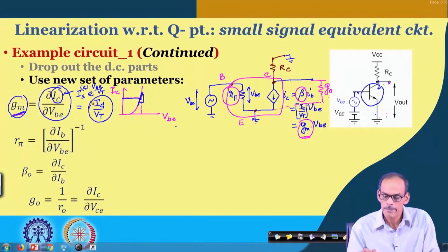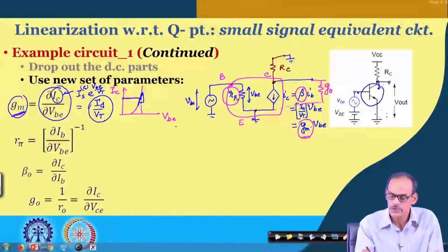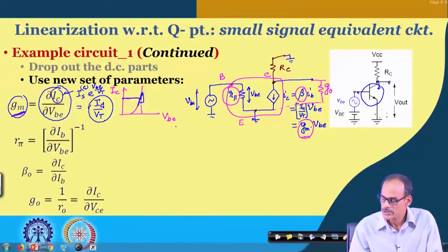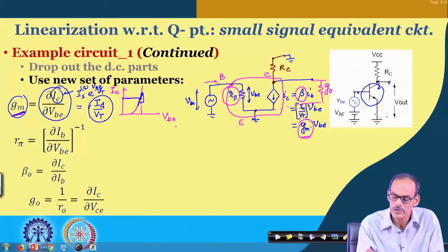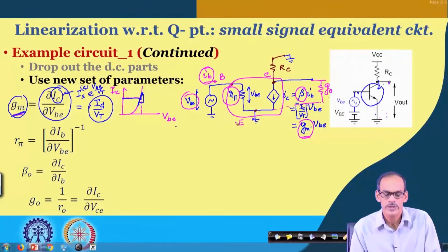On the other hand, whatever current flows through this circuit in the small signal equivalent circuit, say this current is flowing through the base terminal and is IB. So, if I vary this voltage, this current changes. If I take the ratio of these two, then we may say that yes, it is basically the base to emitter terminal conductance.